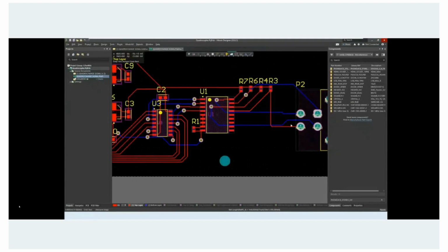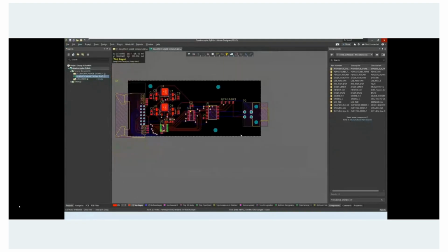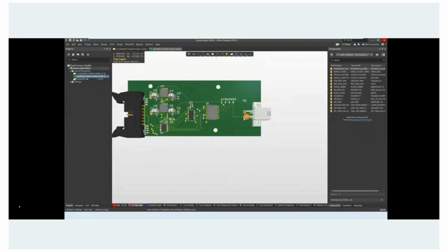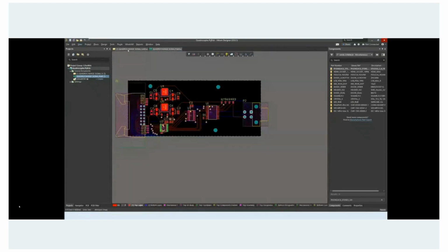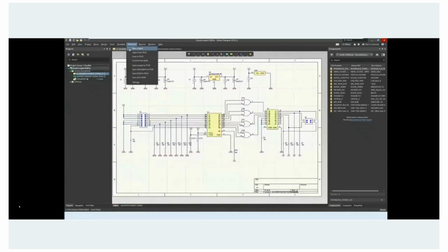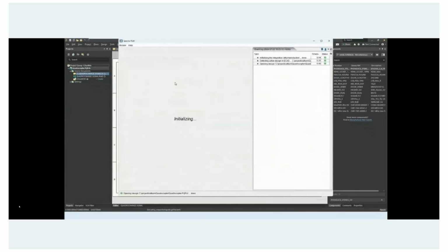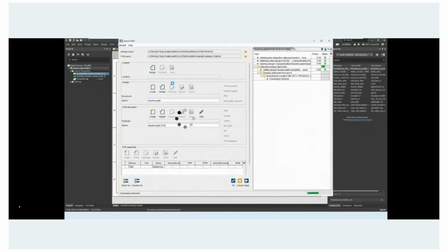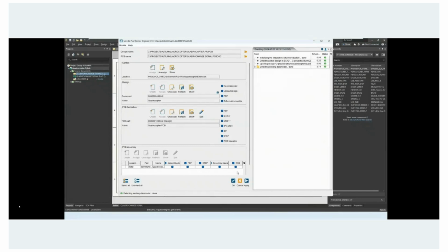I'm going to go into my CAD tool and I'm going to change that part. I've changed the part, I've rerouted it. And if you remember what the old connector looked like, this connector looks different now. We've replaced it with a new part. So what do we do? We save that design back into PLM. It'll overwrite the old BOM with the new BOM that contains our new part, right?